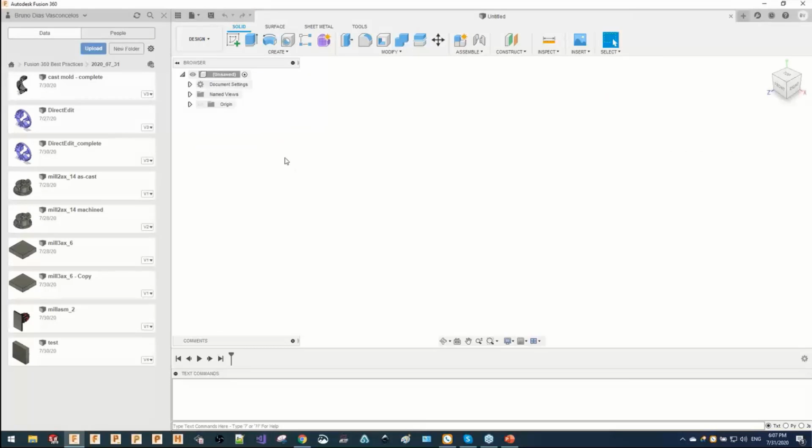So today I would like to bring your attention to a couple of things about using STL files. When you have other CAM systems or other software, some of them allow you to export STL files. You can use those STL files to calculate rest machining, or to represent your stock material.